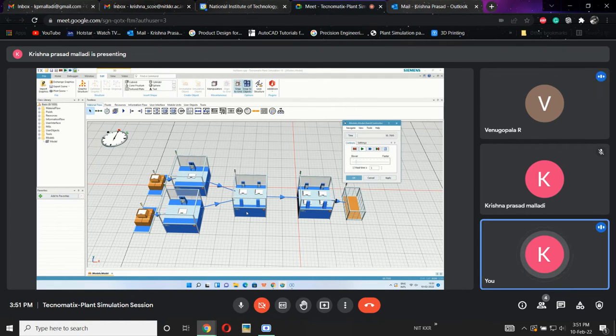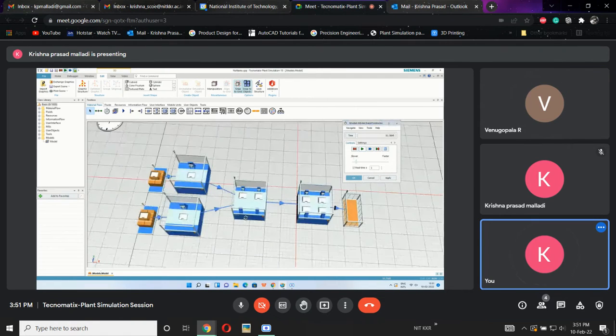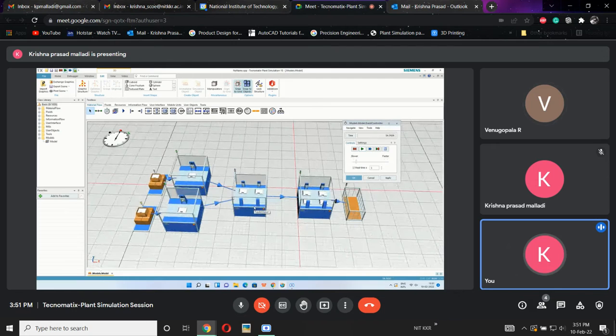That is one of the advantages of these parallel stations. Generally we use this in special applications, when there is a job with fixed production, a fixed layout, where the part is fixed and the machine needs to be kept over there, and some process needs to be taken care of. In those applications we use these parallel stations where simultaneous work is processing.